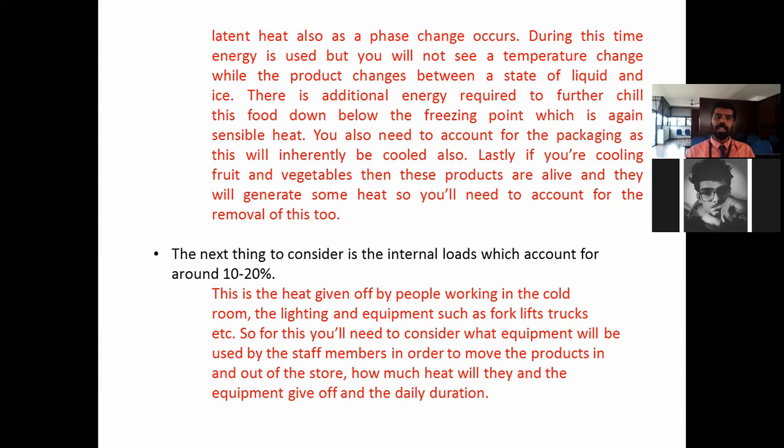Now the next thing to be considered is the internal load, which will account for around 10 to 20%. What is that? What is an internal load? This is the heat given off by people working in the cold room.